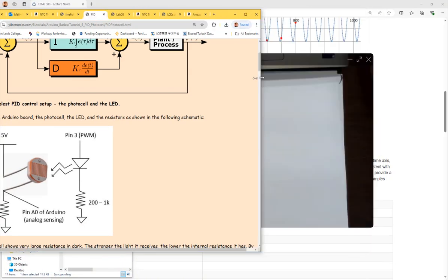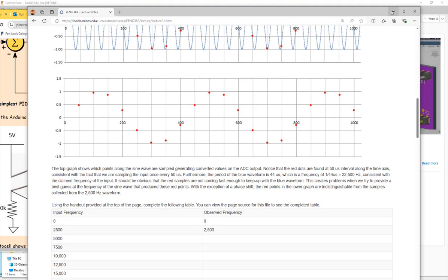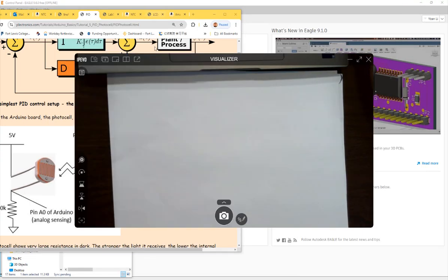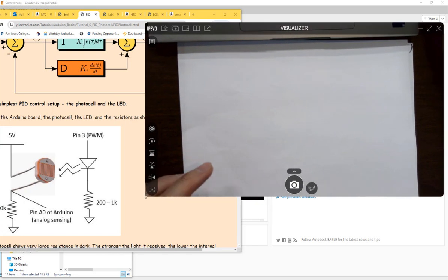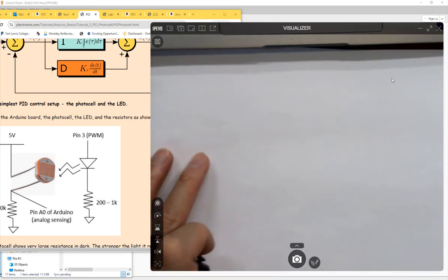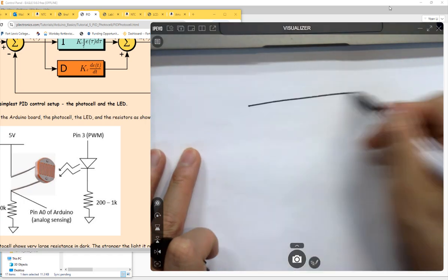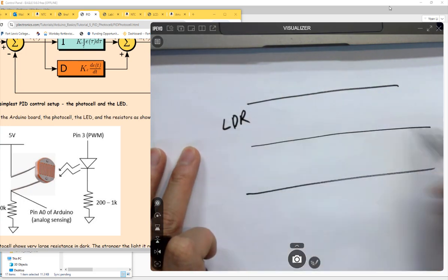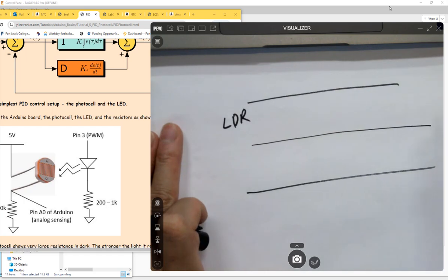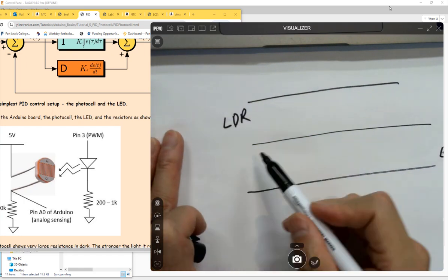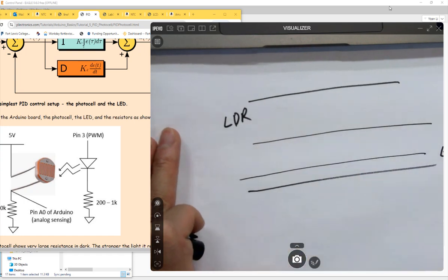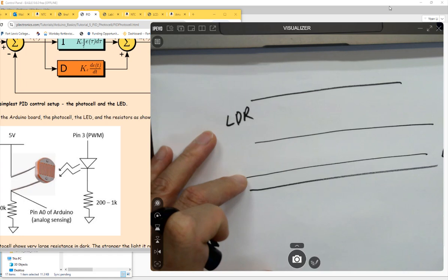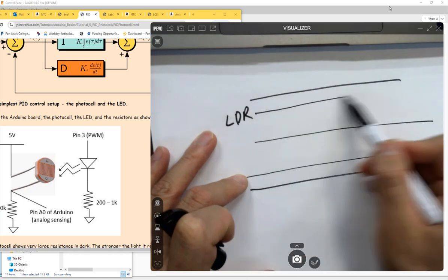If you work on this project and implement it with PIC, you don't have to do the PCB, okay? You can test it on the PIC board you have starting next week. So for example, this is the LDR, light dependent resistor. It's giving you a reading here. That's a set point. And you have an LED over here you can manage. You just turn it on, you test it first, you see the signal comes here, drops to here. If you turn it off, the signal comes back to here.